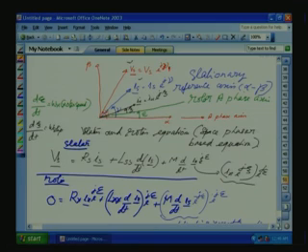Now this voltage space phasor generates three phase currents. So we have an equivalent current space phasor definition, but this voltage and current are not collinear. There is a phase difference. But instead of worrying about the phase difference, we are only taking the angle of the space vector with respect to the A phase axis. So Is has an amplitude and e raised to j,